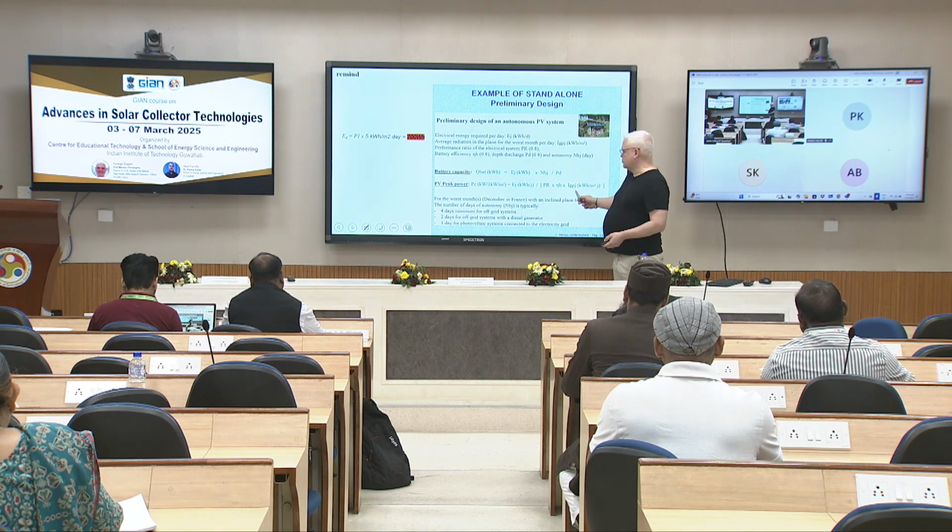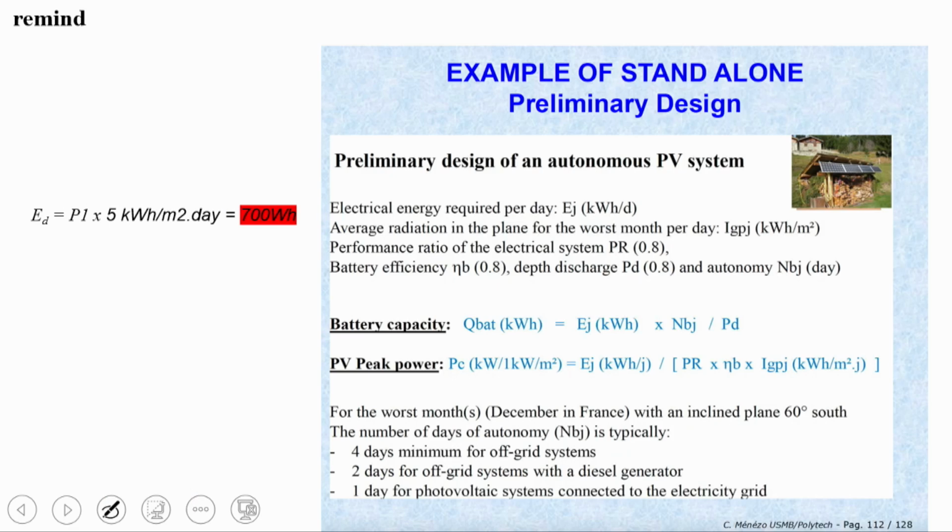Okay. So if we look, we are doing the reverse. We know the energy, we know the power peak. We a priori select a panel, okay? And we don't have to forget that it is for standards. So when we say that the peak power of PV panels is 140, as we select, it is 140 watt per 1000 watt per square meter in standard condition.